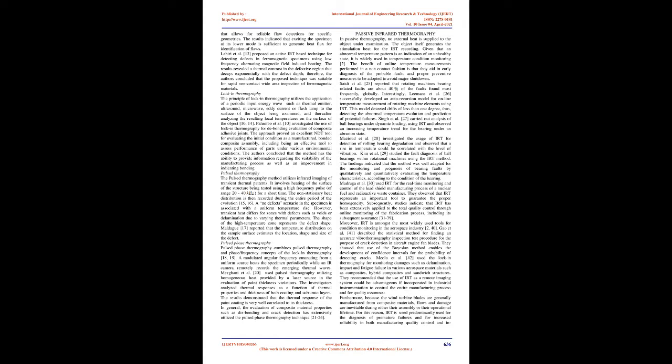Lock-in thermography. The principle of lock-in thermography utilizes the application of a periodic input energy wave, such as thermal emitter, ultrasound, microwave, eddy current or flash lamp, to the surface of the object being examined, and thereafter analyzing the resulting local temperatures on the surface of the object.